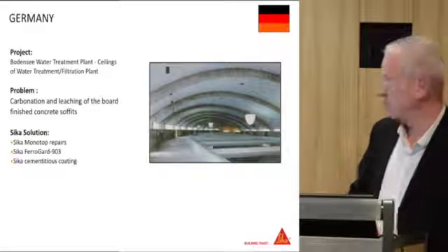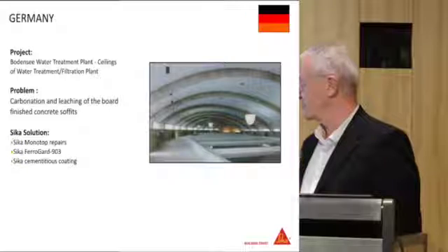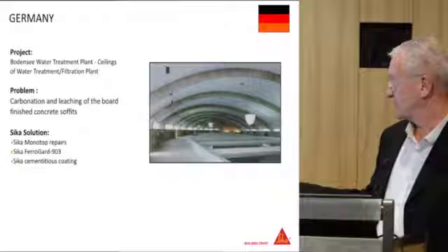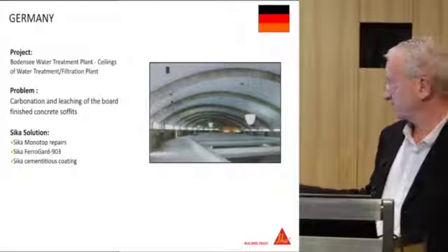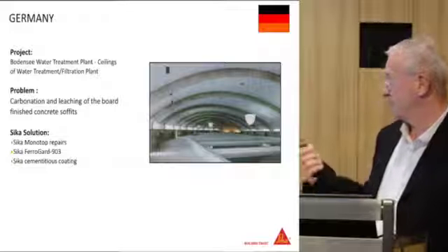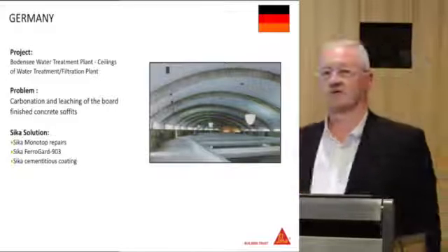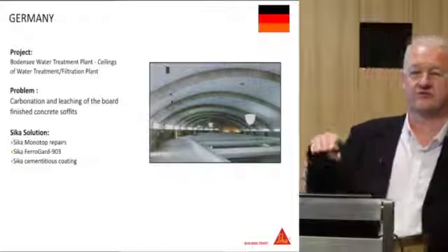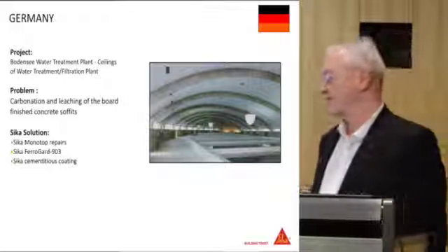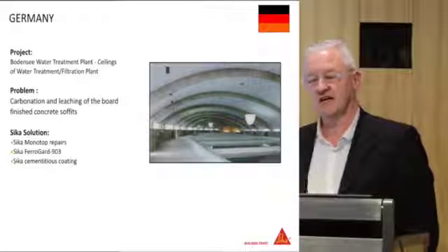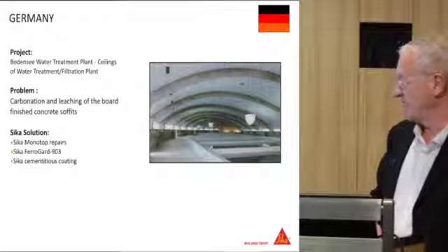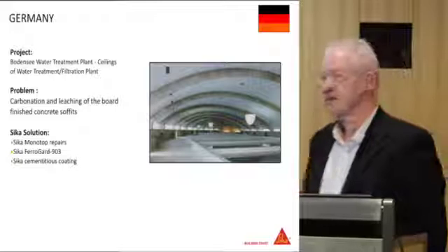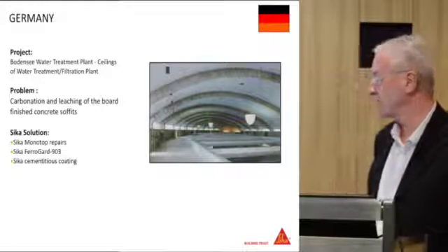And Germany, this is a water treatment plant. This can cause a few problems, certainly where you've got the soffit of the structure, which gets a lot of condensation on there, a lot of attack there, carbonation. But of course, being water, they don't want to use systems that are going to contaminate the water and cause problems further down the line to people's health. And that's the advantage again of the inhibitor that we have. It's water soluble, and it doesn't cause any problems if it does fall into the water. It's not carcinogenic, and it's very easy to use and good for the contractors as well.